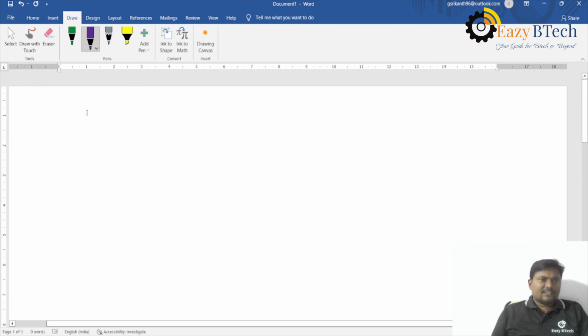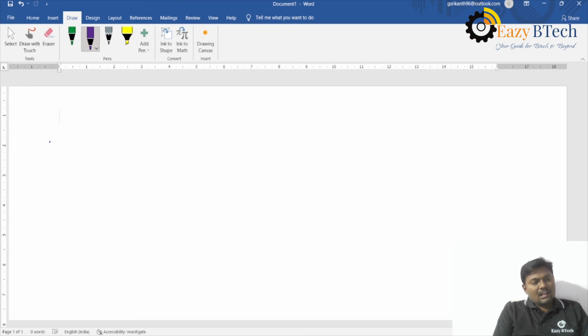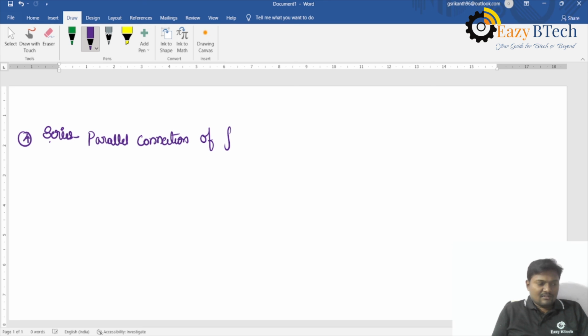After that, one more method is there. We discussed the field diverter control, armature diverter control and tapped field control. The fourth method is series and parallel connection of field. So this is T by 2 and T by 2, and the total turns is T.